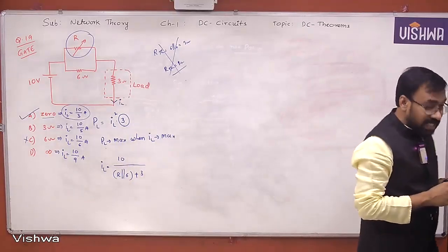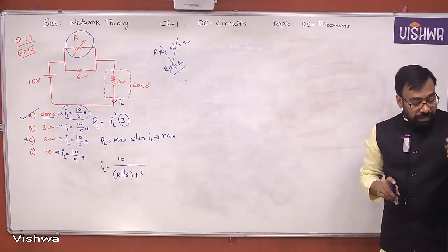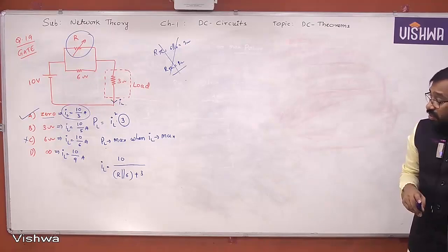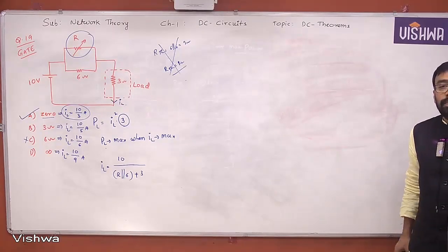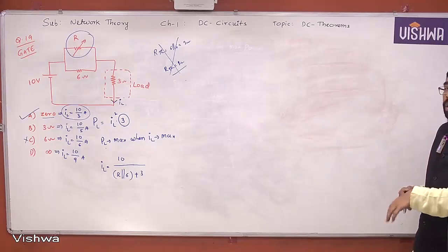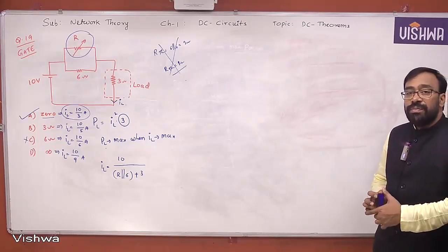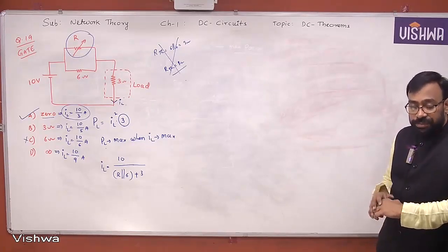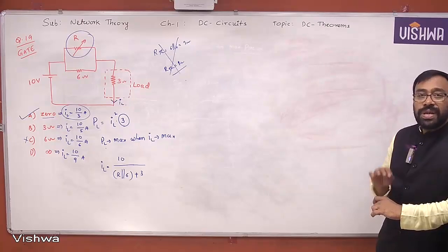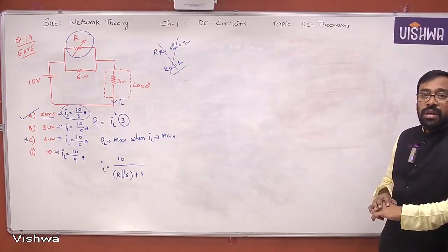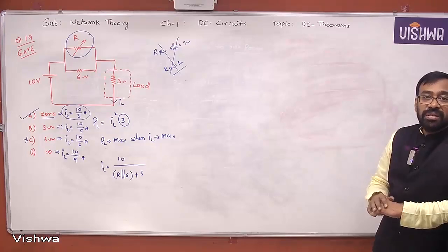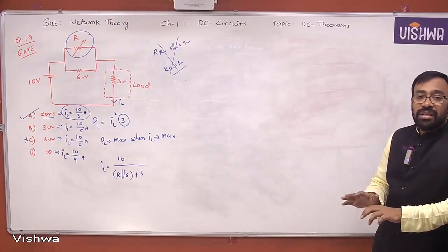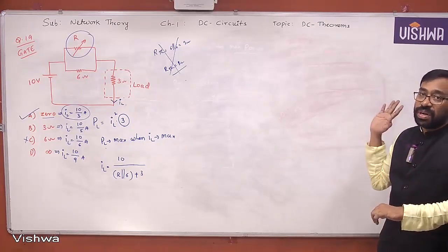I think all of you understand this. So remember once again, whenever you read the term maximum power transfer in a problem, don't come to a conclusion that the problem belongs to the maximum power transfer theorem. It all depends whether the load is variable or not, whether you are varying the load and sending the maximum power to the load or not. If that is not there, then the problem does not come under the maximum power transfer theorem.